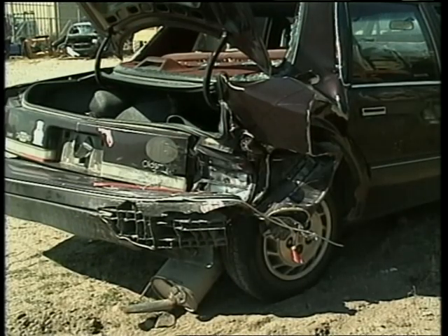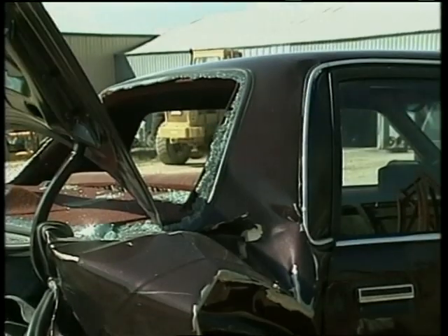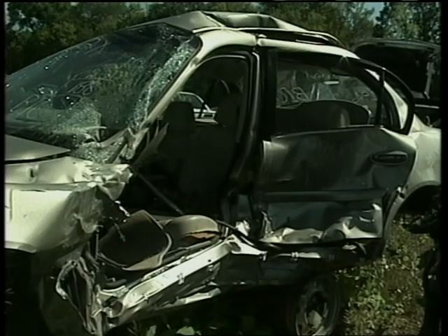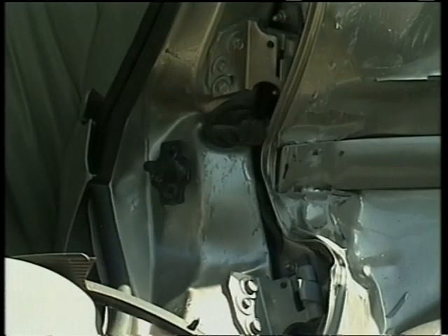Rear unibody damage starts at the bumper, moves to the back panel, trunk lid, and floor pan. If the force is greater, it'll affect the quarter panels or even the pillar. Side unibody damage will cause the door, front section, center body pillar, and even the floor to deform. Energy from top impacts can be absorbed into the roof panel, roof side rail, body pillars, and quarter panels. But before any repairs can be made, measurement is critical.